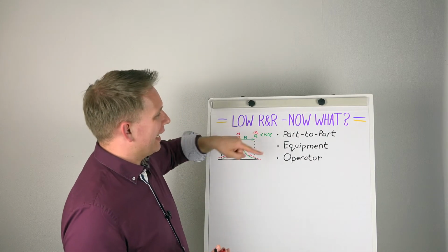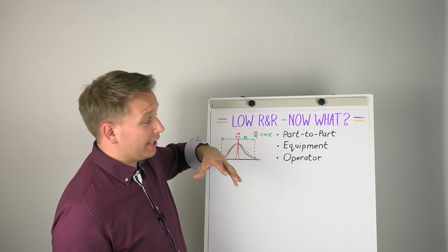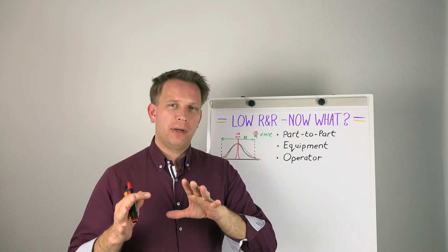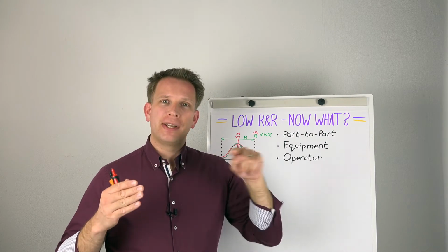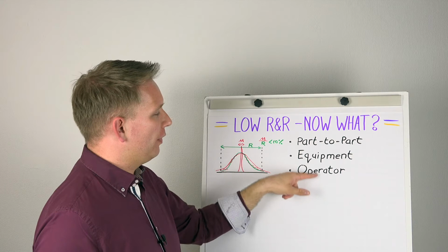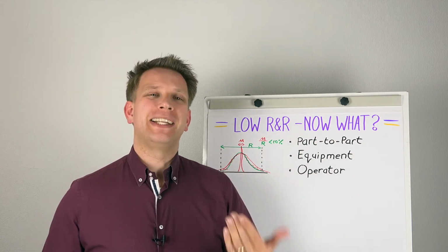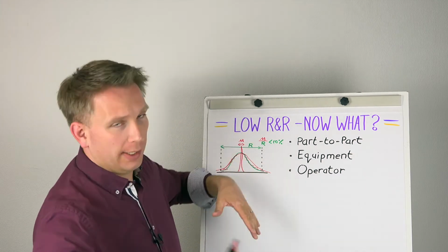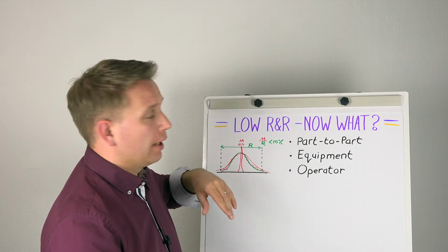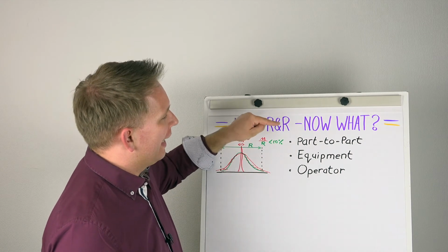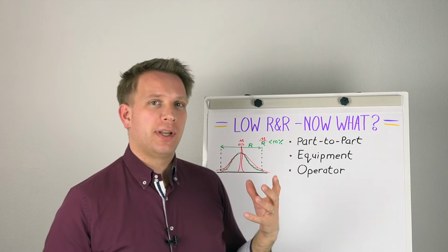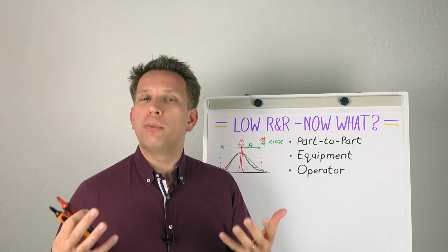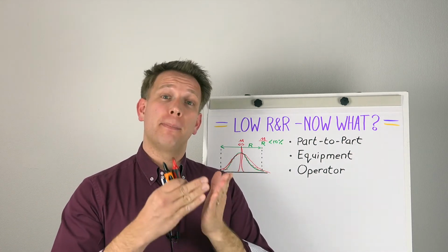And that means that we can then calculate, using statistics, the difference. See, each part is then measured, and we take the 3 by 3 by 10 here. It's measured 9 times. So one operator will be measuring 30 times. 10 parts, 3 trials. That means that in the end, we have a whole load of measurements. Every part, because it is measured 9 times, we can take a nice average, and all of those measurements will make sure that we get a pretty accurate measurement of this part.